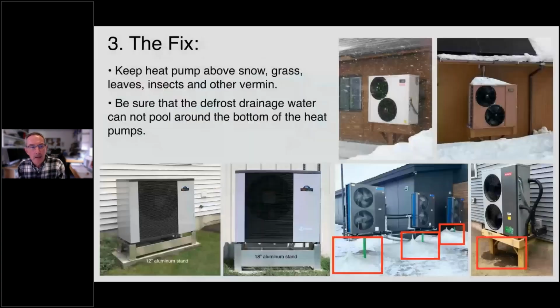Okay. So what's the fix? To get the unit up in the air. Over here in the upper right, those are actually two photos of the same heat pump. You can see that stand would normally hold that heat pump about the base of it about 3 feet. That's in an area that gets a lot of snow. This winter, the snow got pretty close to the base of that heat pump. It was probably within a little less than a foot.